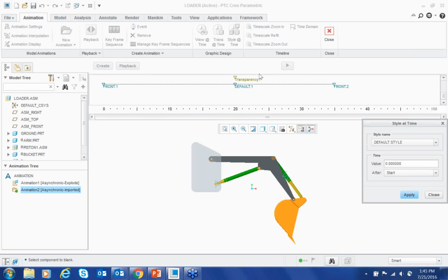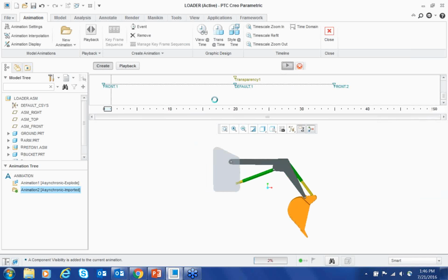So, for this current model, I want the system to start with our default display style at the beginning of the analysis. Once that is done, I want the system to automatically toggle to the style 1 that we created for this assembly over here, and I want the system to do it after halfway along the timeline of our animation. So the total duration of our animation is 50, so I'm going to place it halfway, that is 25, and we'll go and verify it.